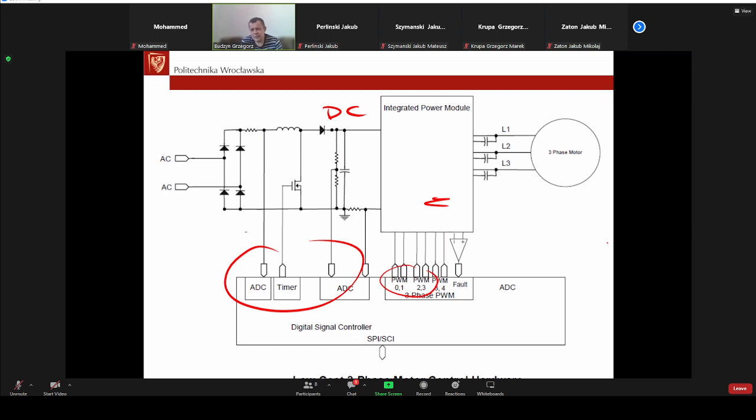If not, my last comment about the DSCs is that today it's pretty difficult sometimes to discern a DSC from a microcontroller, unless it has a special name like DSP. So there is a DSP, which is different from PIC24F, but in the case of Cortex-M4 especially, they share a lot of features from DSPs, which means that we can classify any Cortex-M4F processor as a DSC, yet they are classified as microcontrollers.